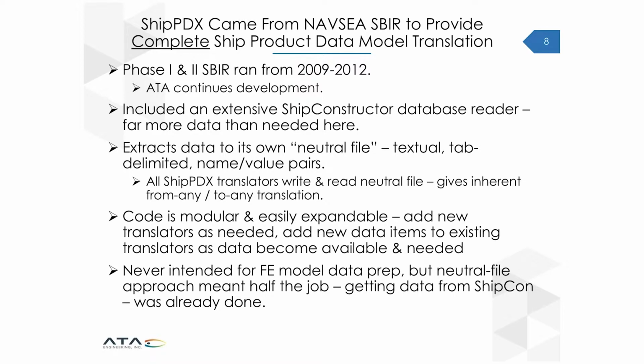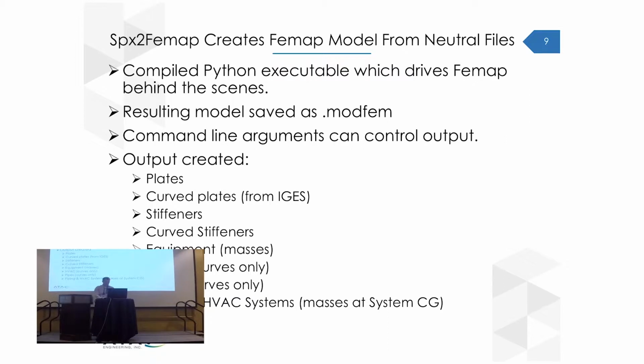whatever you're analyzing. So the kind of the core of what we created was SPX to FEMAP. So this is a compiled Python executable. It basically runs FEMAP from behind the scenes. So what happens is it opens up FEMAP, it reads in all the files that ShipPDX has exported, and it does a whole bunch of API commands. So they're very similar to the same commands that you would have done kind of by hand as an analyst, but these are all things that can be automated and save a bunch of time. And then at the end, it basically saves its current state so the analyst can open it and continue to